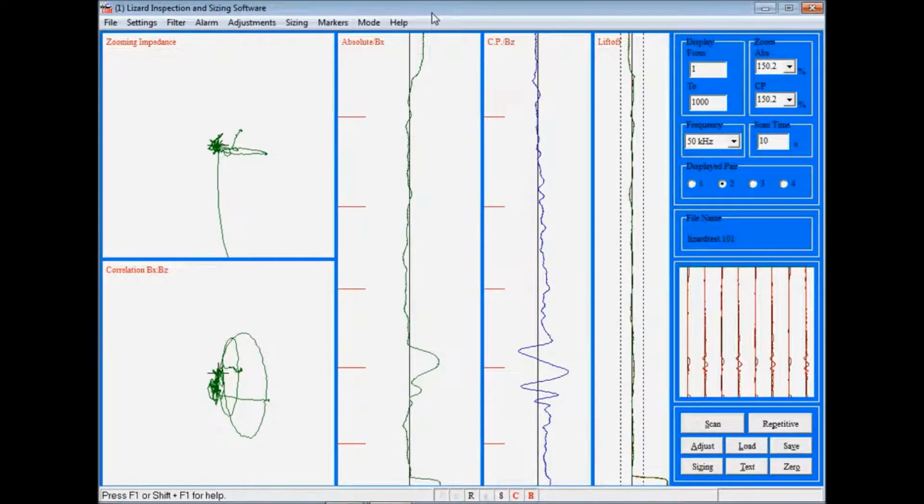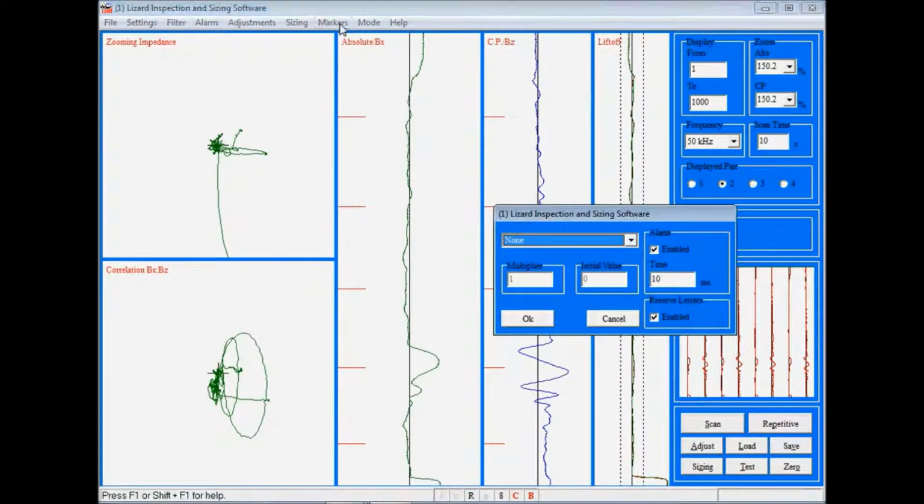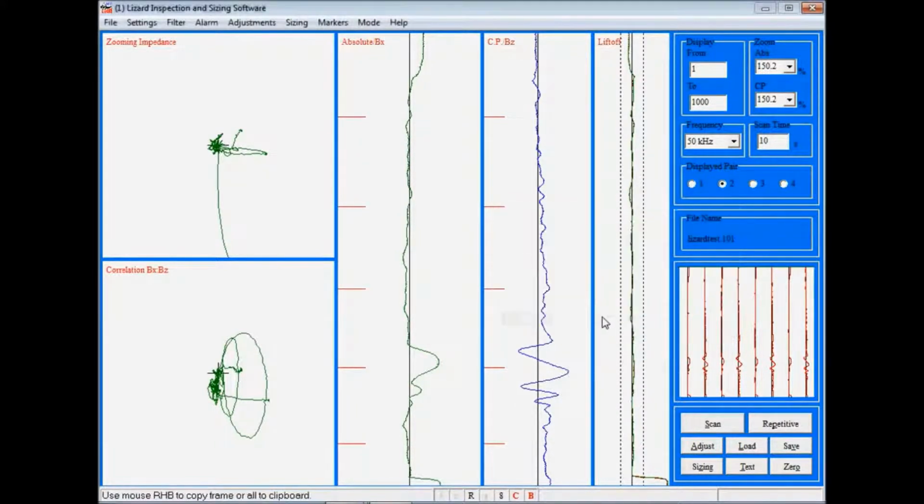Okay, we've now got a scan of an unknown plate, a full penetration butt weld. We use the repetitive function to quickly identify an area of interest for us to look at. And then we performed the scan, and we put these marker points in as just simple strikes across the data. We do have options up here to change the markers to be actually identified, so whether they have keyboard entries to them, or whether, as you press the keys, they count up in multiples. There's lots of options in there for identifying the markers. In this instance, we'll just use the basic strikes.